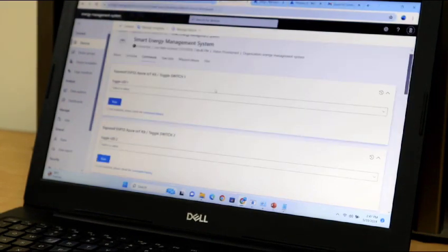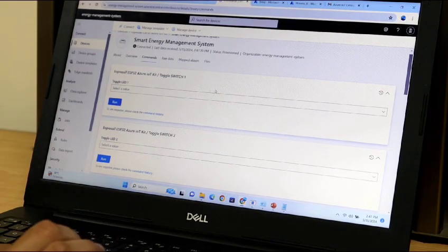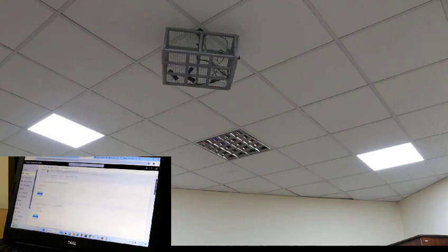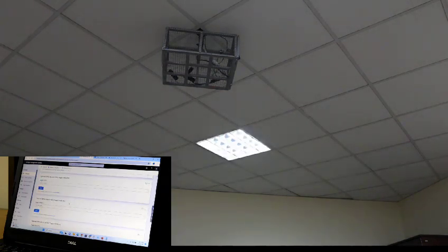Now the second portion is remote control. We have different commands on our IoT Central application, and we can switch our appliances easily using these commands. For example, this is the toggle LED one. If I turn it false, then it will turn off our first appliance. Similarly for LED 2, and now I want to turn on our LED 3, so I will select true, then it turns on. So these commands help us to easily access our appliances anywhere in the world.